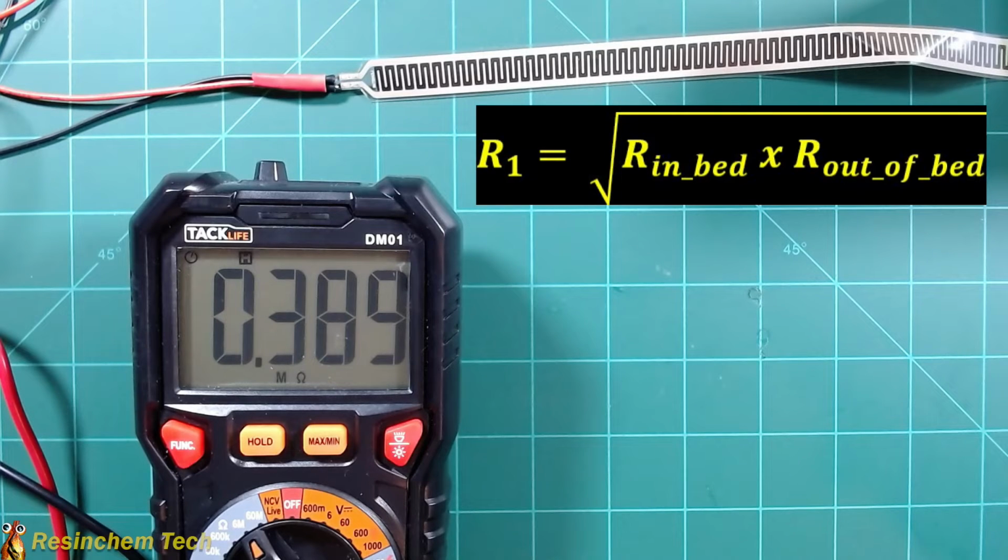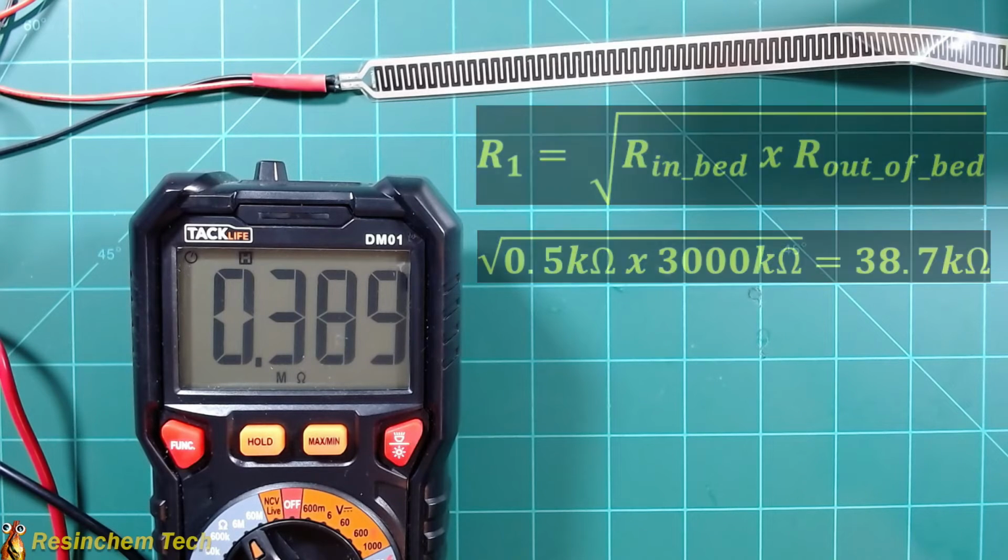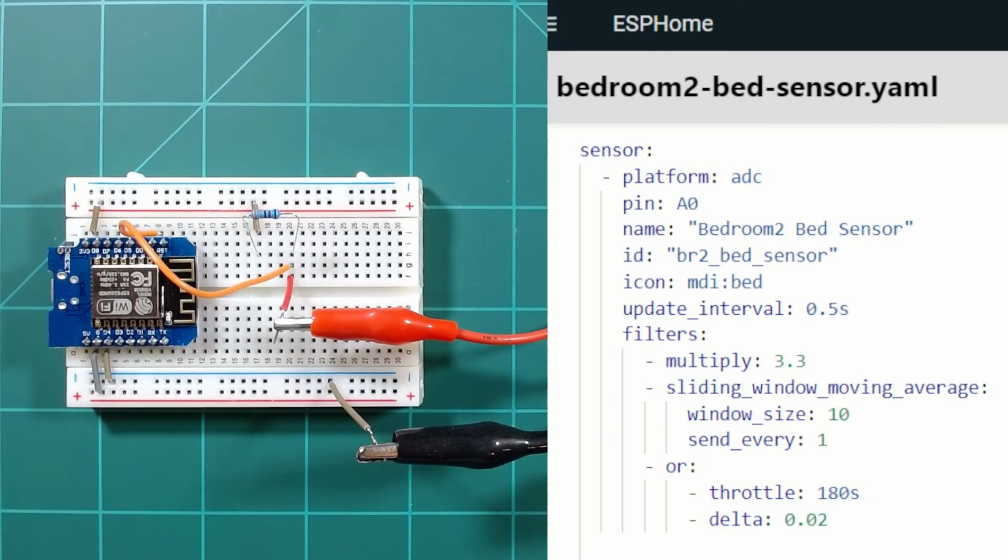But if we drop that into our calculations, converting everything to kilo ohms, we have about 3,000 kilo ohms times 0.05 kilo ohms. Take the square root of that, and it gives us a starting resistor value of around 38.7 kilo ohms. So that's where we'll start out, and then we'll fine tune that doing a bench test on a breadboard.